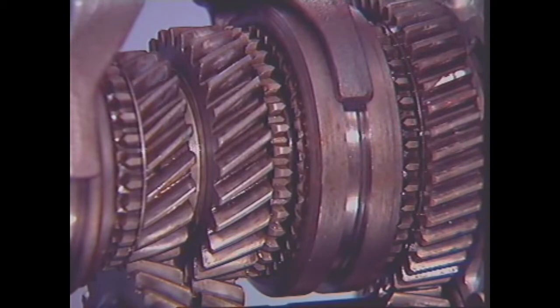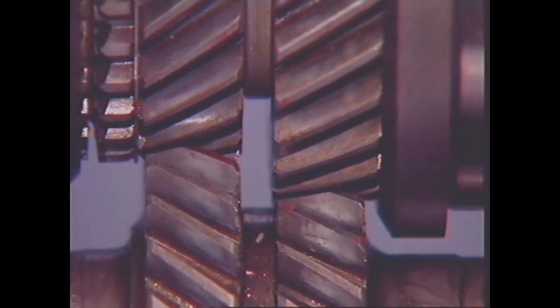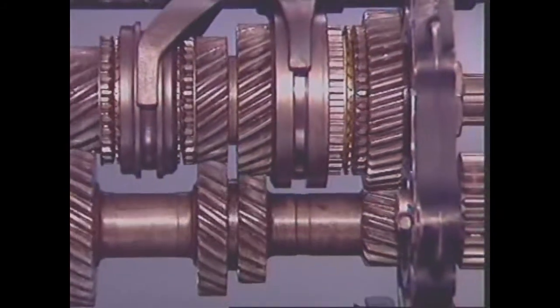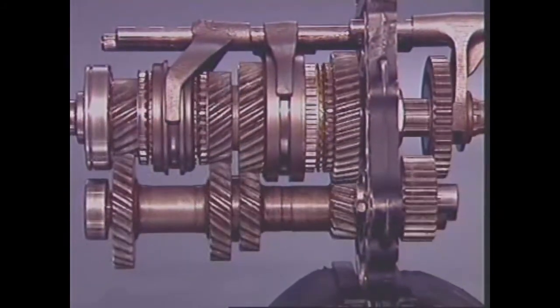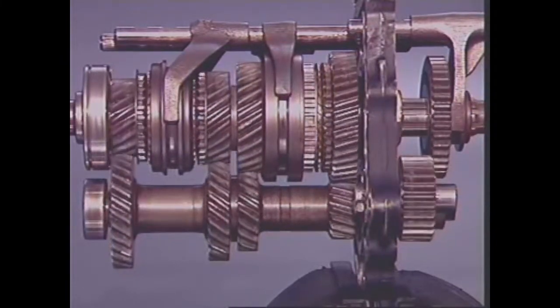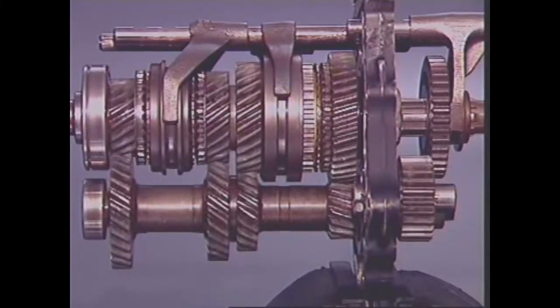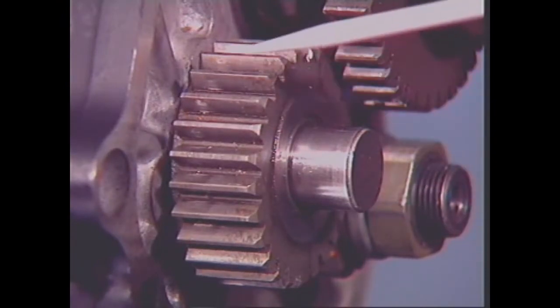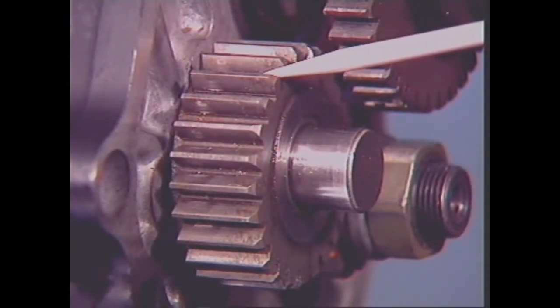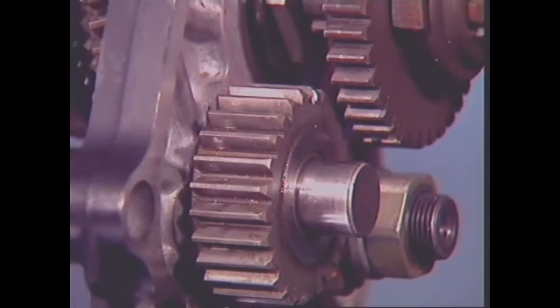Before engagement of the components occurs, a synchromesh device between the sleeve and gear synchronizes them. The gears constantly in mesh have their teeth cut on a helix at an angle to the gear centerline. This reduces gear noise and distributes load more evenly, as several teeth are in contact at any one time. Teeth on the reverse idler are normally straight cut or spur gears, cut parallel to the gear centerline.